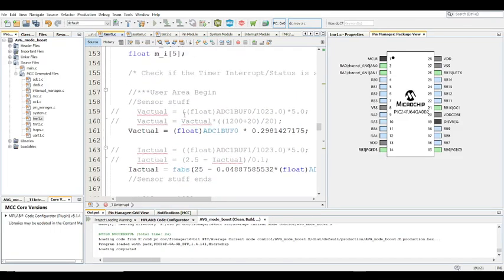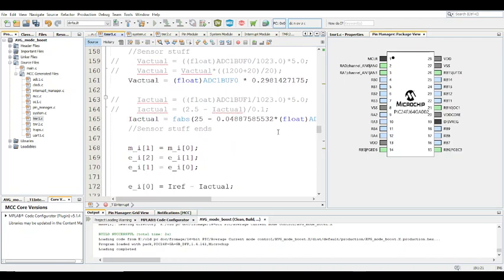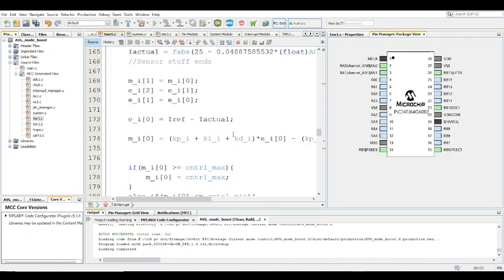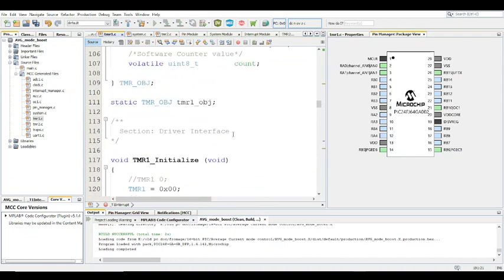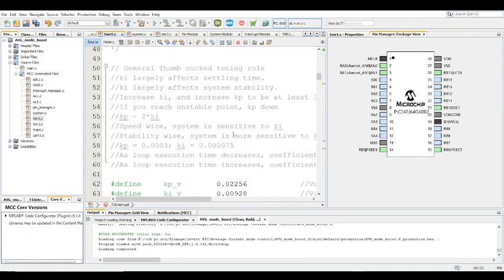And that's how you do that. And for instability issues, always start with these set values. KP 0.003 is super slow, right? Control is so slow you can notice it trying to get to the set point, which is really slow control, especially for DC-DC converters.